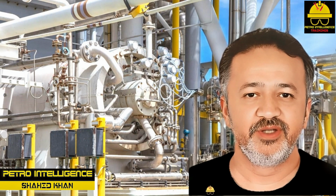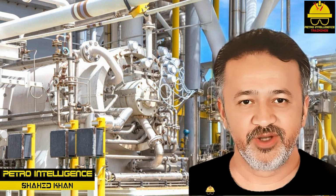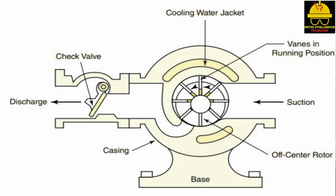Sliding vane compressors. The sliding vane compressor uses a slightly off-center rotor with sliding vanes to compress gases. The major components of a sliding vane compressor are shown in picture. The gas inlet port is positioned so that gas flows into the vanes when they are fully extended and form the largest pocket. As the vanes turn toward the discharge port, the gases are compressed.